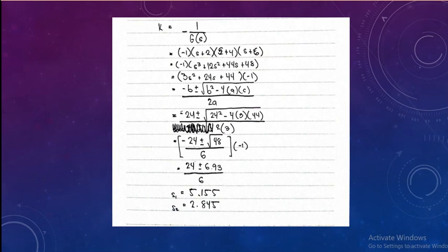So for our breakaway point, we use the formula −1 over G(s). As we plug in the data, we can see that −1 times (s + 2)(s + 4)(s + 6) makes up our G(s). We didn't put the basic form because we moved directly to our working equation. As we expand this, using the FOIL method on all 3 factors, we come up with s cubed + 12s squared + 44s + 48.